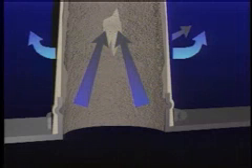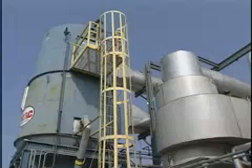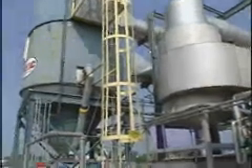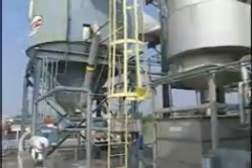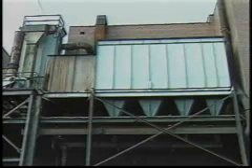Acid condensation will weaken the fabric material, causing holes to form. Moisture or organic vapor condensation can cause portions of the fabric to blind. When a portion of the fabric is blinded, the remaining fabric will operate with a higher airflow than intended, which can cause particles to seep through the fabric. An increase in the temperature difference across the collector indicates increased air infiltration. Acid, moisture, or organic vapor condensation problems can develop in portions of the collector if the cooling is excessive.